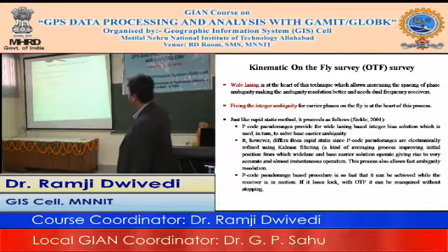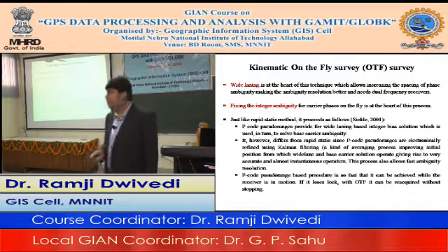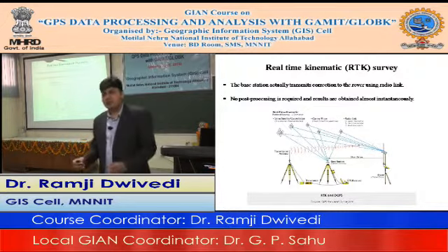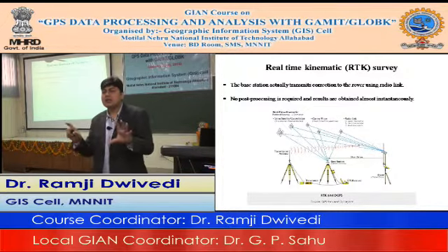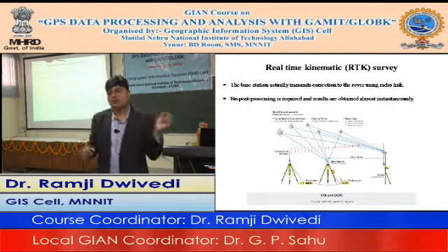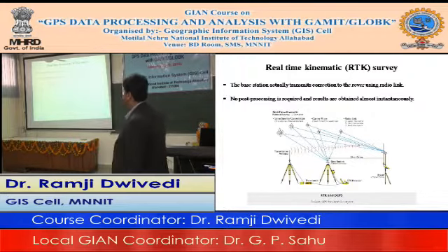Okay, so this is RTK, which is nowadays also used for the so-called high precision work, where the base station transmits corrections to the rover. Although the word kinematic is in the sense that sometimes you can move your receiver, generally the RTK word is given for the rover position in static mode, and you are transmitting corrections in a real-time manner for the carrier phase solution.